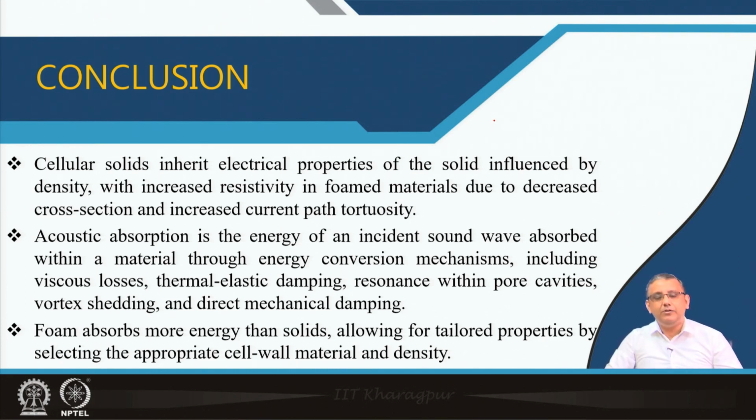And third, we learnt about the application of foams for energy absorption. We learnt that it is very important to identify the peak stress of the foam at which the energy absorption is required, and for that the stress-strain curve of foams under compression, like the elastic part, then the plateau part, and the densification part, is very important. We need to identify the optimum foam density for these applications, and based on that the optimum amount of energy will be identified.